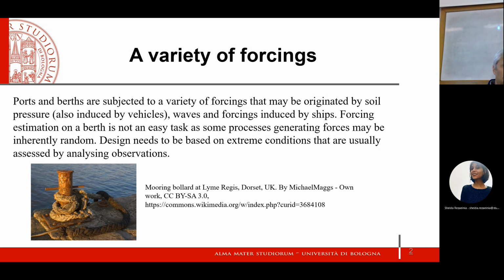This is often done in coastal engineering, hydraulic engineering. We pick up the worst event in the past. If the past is long, if we have a long history, this is perfectly fine. If we have 100 years of wave data, which is probably never the case, it is not unreasonable to take the worst event in the past, or the second worst, or the third worst.